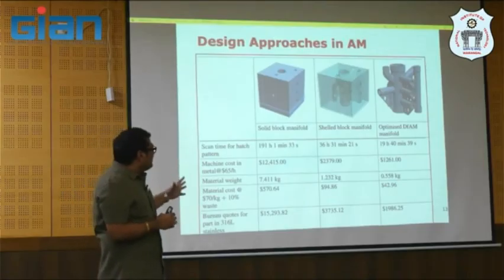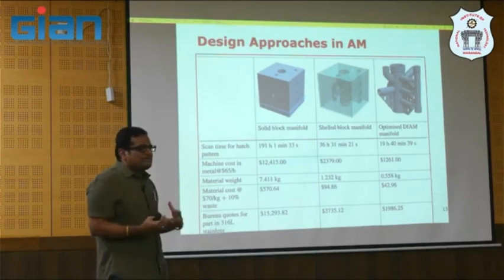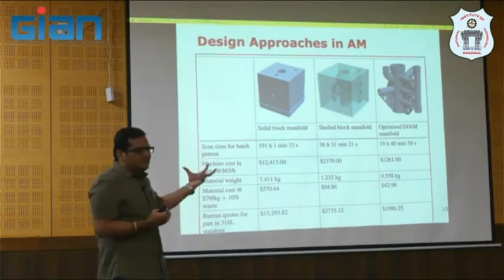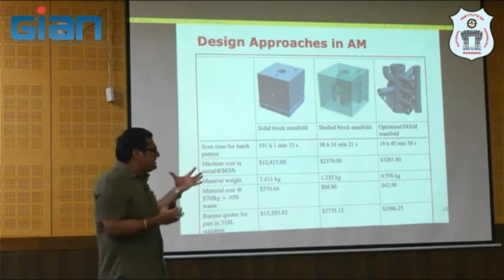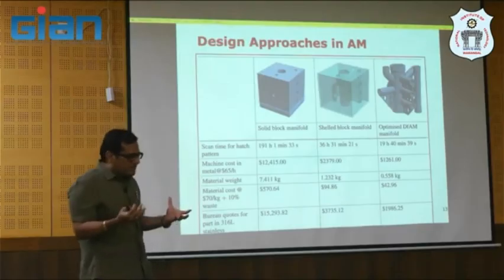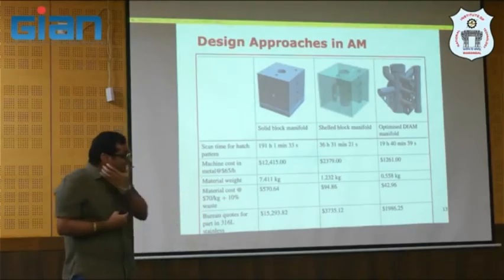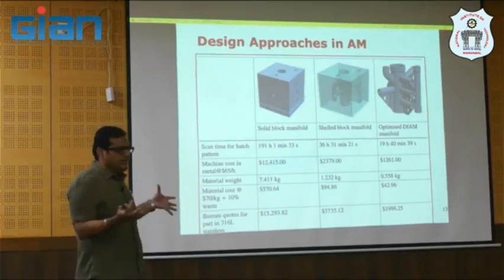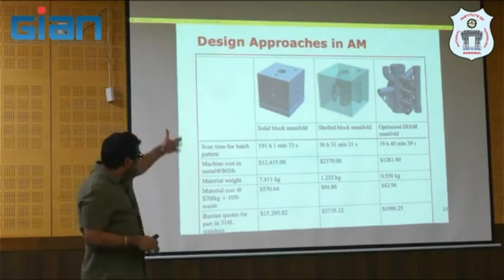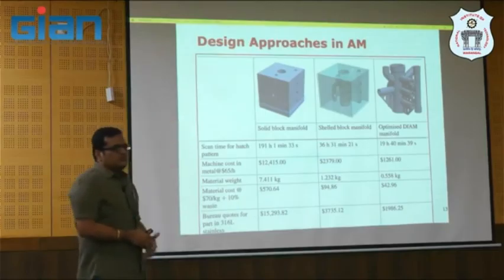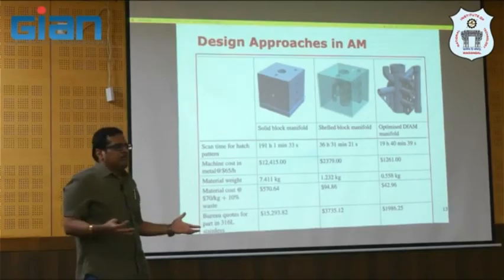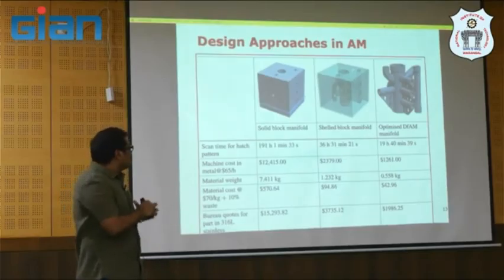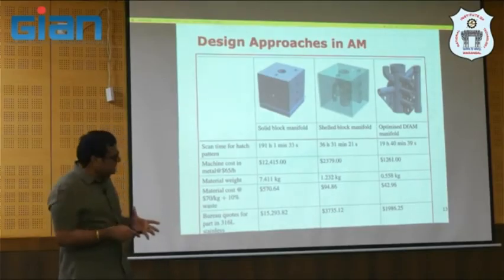So whenever you have a design, you ensure that it is redesigned, in order to get the maximum benefit of additive manufacturing technology. Otherwise, it may be much costlier. If you reproduce the same design, we need to pay heavily, right? So one can understand the importance of design in additive.